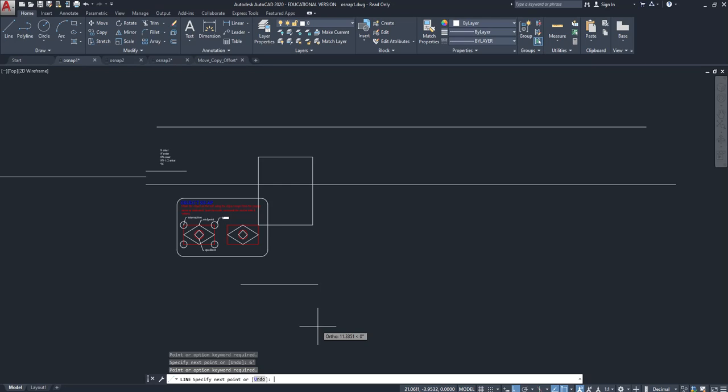So if you're working and you start to try and input something and it doesn't function, that's likely the first thing I'm going to say. I'm going to say, well, are your units correct, right? Is AutoCAD recognizing what you're inputting into it, okay? So escape, escape, easy enough to change the units, make sure it's architectural, okay?